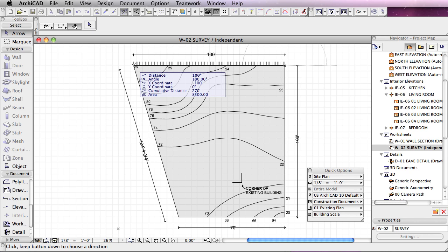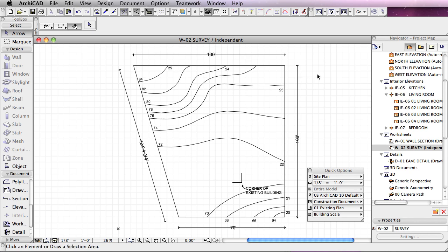For example, if instead of 70 feet, it read a little under 6 feet, perhaps it's 70 inches, and you'd need to bring it in again, double checking that you're not setting it for inches. You need to set the measurement unit to feet, 12 times as big. Or the reverse, you might have something that's way too big and you have to bring it in again with a different scale. Now I'll hit the escape key to cancel that because the measurement was verified.